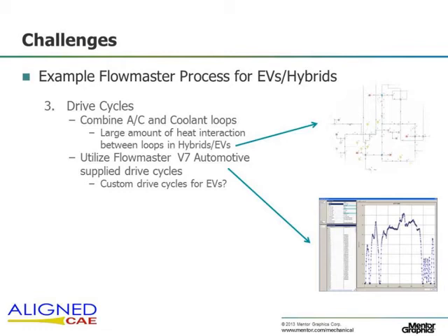We're varying things like battery heat rejection. So over this drive cycle, we have a fixed scenario for all of our components to start with. And we basically get transient plots of things like evaporator discharge temperatures, compressor head pressures, also radiator top tank temperatures. They're the main things that we're really concerned about during these drive cycles.